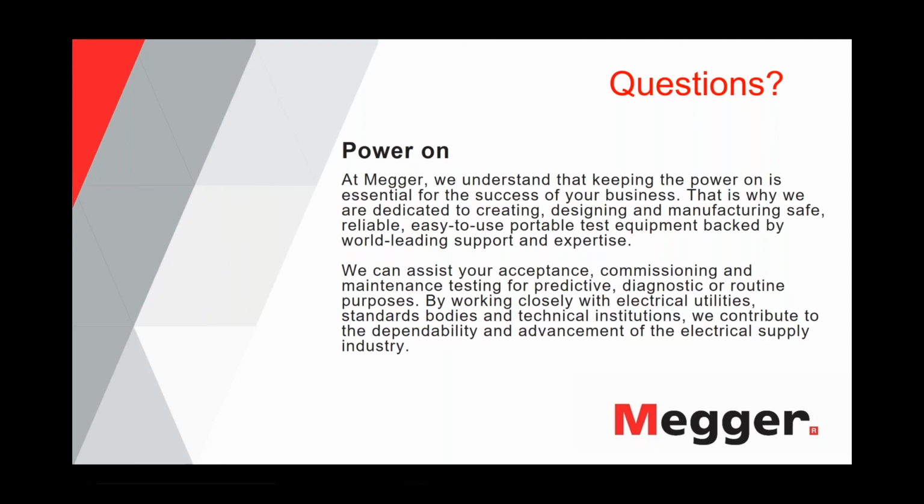So as we saw, you do the test at 0.5, at 1 U0, and at 1.5. Now, that means you don't go even remotely as high as on the VLF withstand tests with the machine. And that also helps that with tan delta, you can do tan delta on cables where if you would just try to do a straight VLF test, you could not handle them.